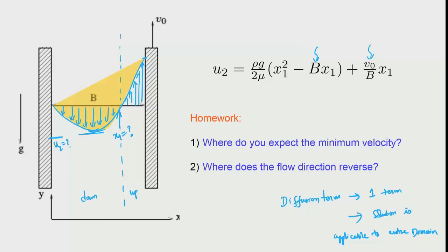And we are also going to look at the reason why this is called the diffusion profile of the velocity field. The reason is that what is being diffused is the momentum. Okay, so the momentum that is being dispersed within the medium because of the wall conditions is the reason why the viscosity is playing a role. So, these are all basically solutions for viscous liquids only, which luckily for us in the metallurgical domain is applicable, because liquid metals and slags are generally very viscous.